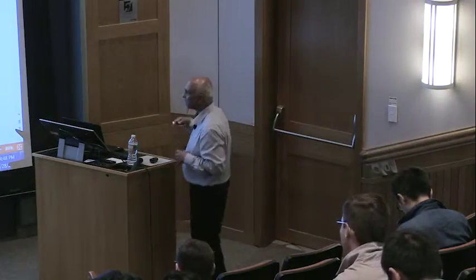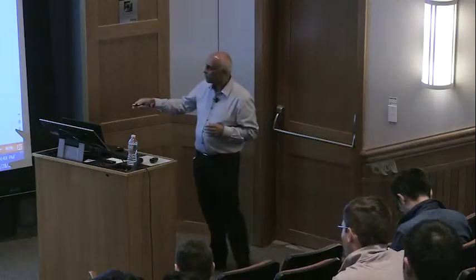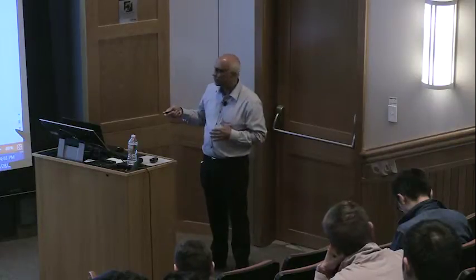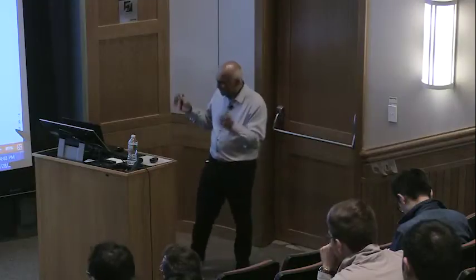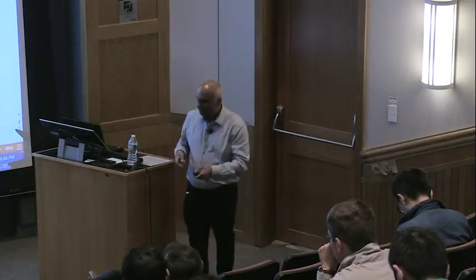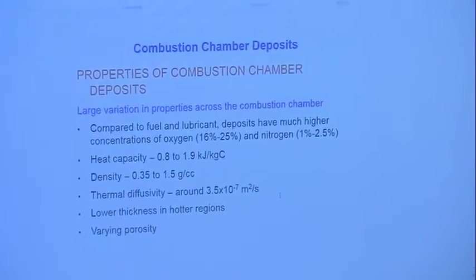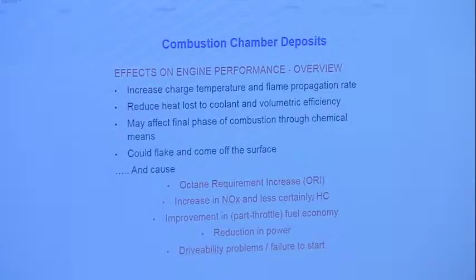Thermal diffusivity has been measured, and in the hotter regions, the thickness is much lower, like near the exhaust valve, for instance. And the porosity is very different. All these things have been measured, and they've been measured for good reasons, because they're trying to connect the effects of combustion chamber deposits to their properties.